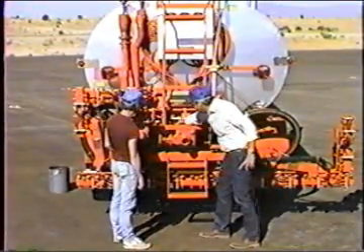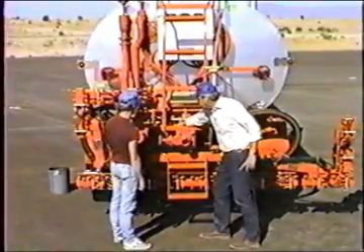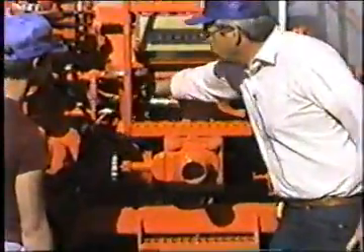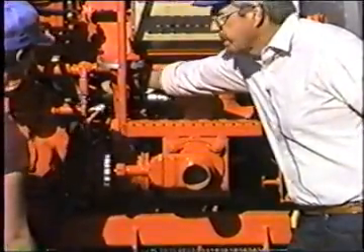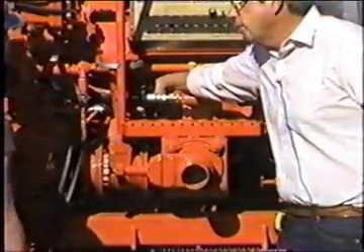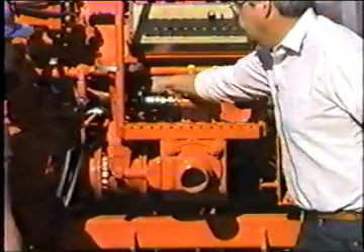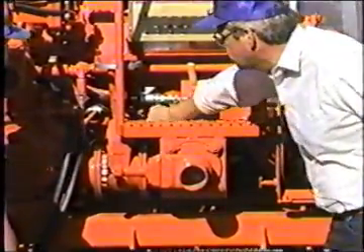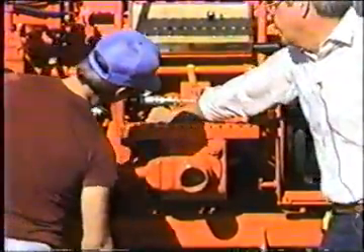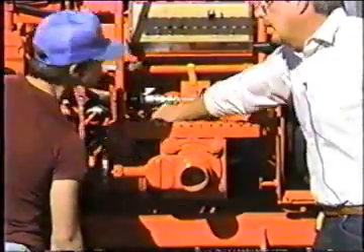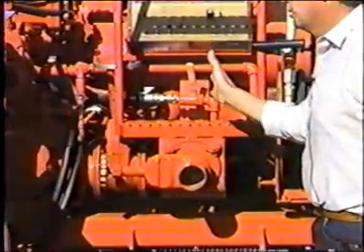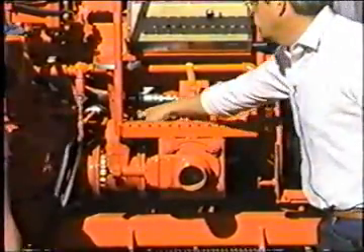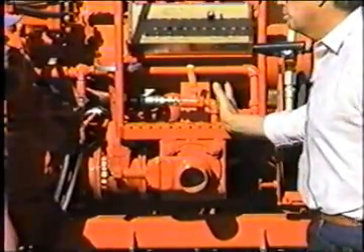Right now, if it tries to go to the left, it gets to a butterfly valve. There's a butterfly valve right here that's operated by an air cylinder. Okay, this is the main equalizer valve, and the name of it will make sense here in a little while. If you look closely at it, there's a slot on the end of that shaft, and that indicates the direction of the blade on that butterfly valve. Right now that valve is in the closed position because that slot is crossways or perpendicular to the pipe.